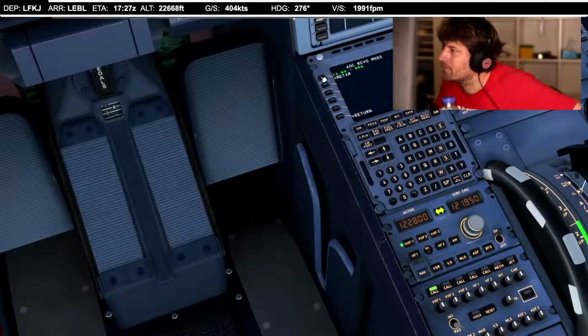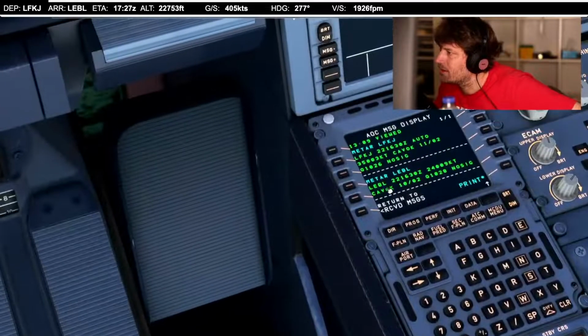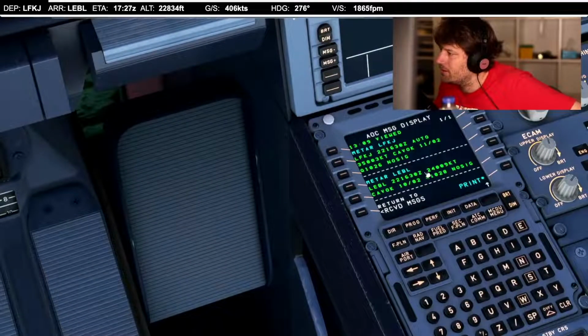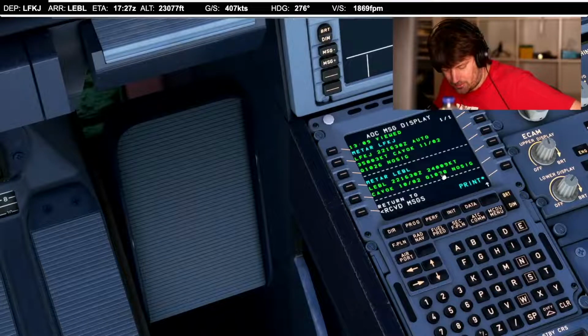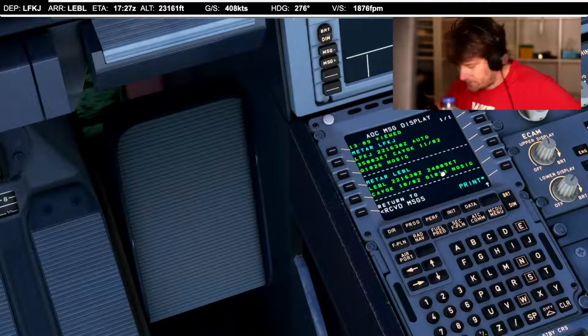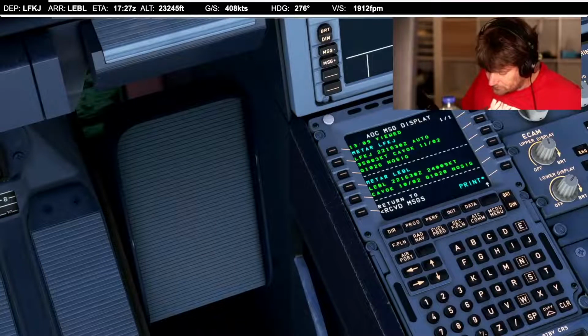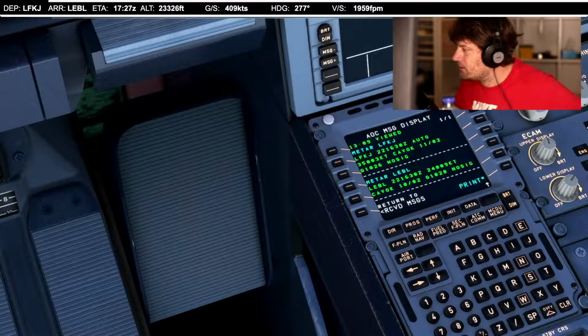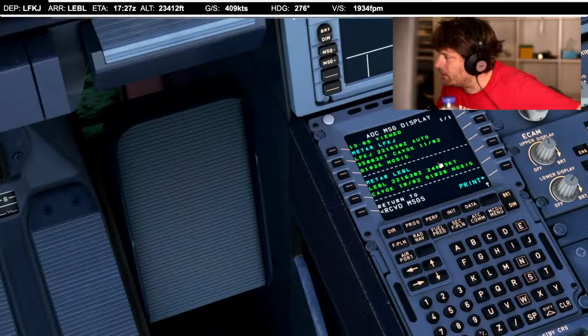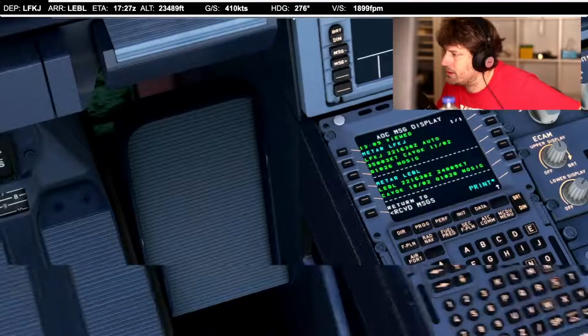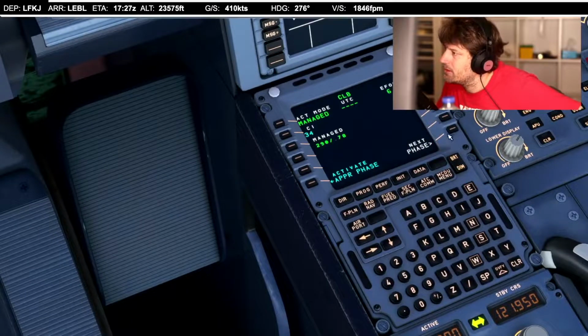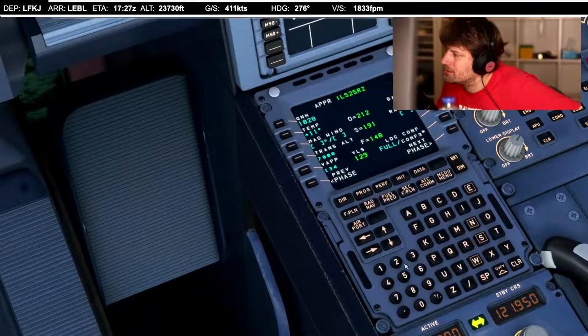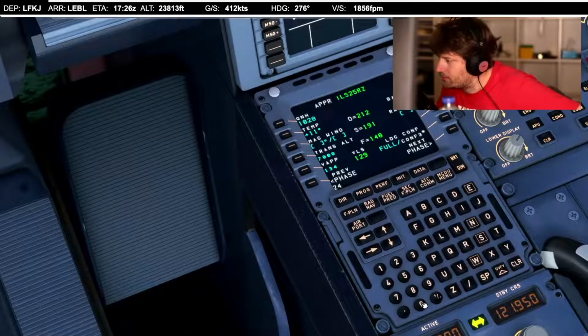There's our METAR. Barcelona 240, 9 knots. QNH of 1028. So the wind turned a little bit, but even in a more favorable direction for the runway that we're choosing. So let's put that information already into our performance page. 240, 9 knots.